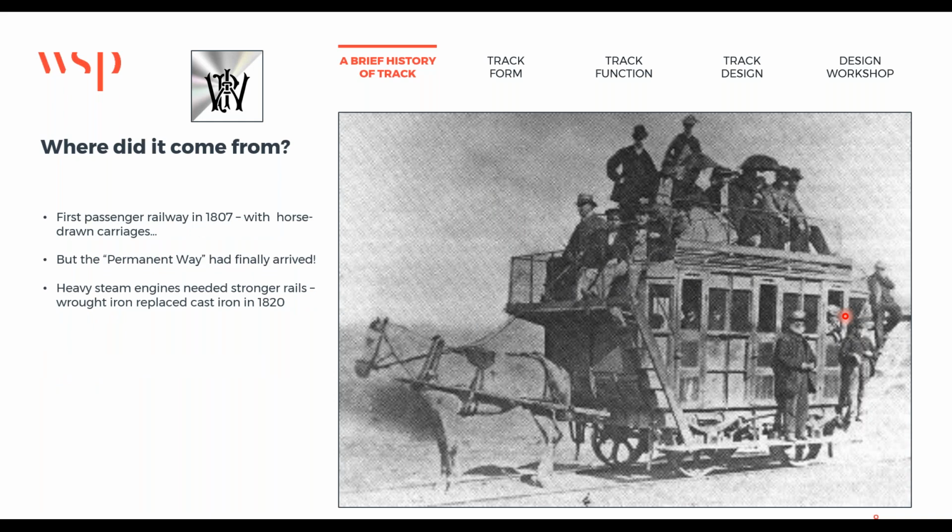The term permanent way was first used when the early railways were being constructed. To enable the excavation and transport of the huge volumes of material that were involved, a temporary railway, occasionally of narrower gauge, was created. The permanent railway, or layout of running lines, was then constructed once the bulk earthworks were completed. And we still use this method today in certain circumstances. We use the track next to the track we're trying to renew or build as a method of transporting the materials.